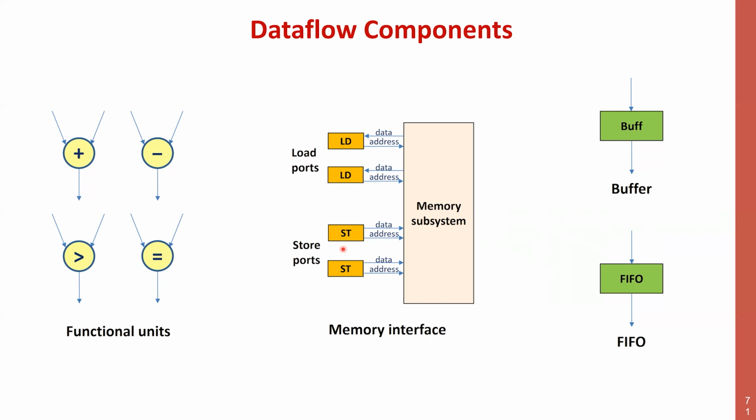By the way, if you know a bit memory systems, they typically have some handshaking interface. So it's probably the memory interface is the most standard version, right? You give the address and you say, hey, I have an address for you to do a load, and you get the data, and somehow the memory system says, oh, look, here is your data, because who knows when the memory system is going to answer, which again is relatively normal for a memory system.